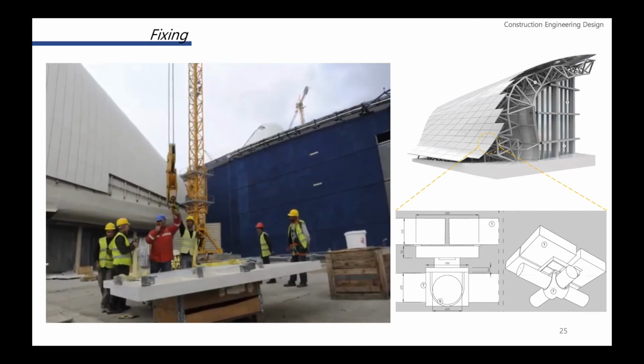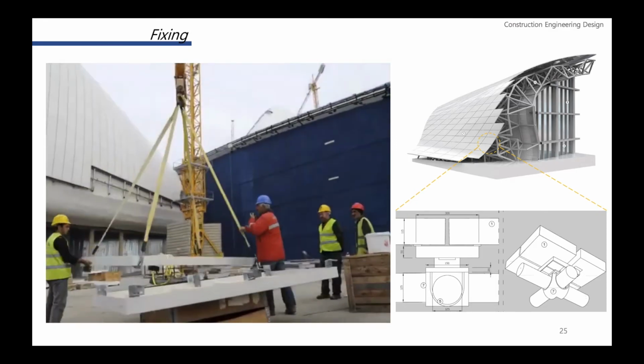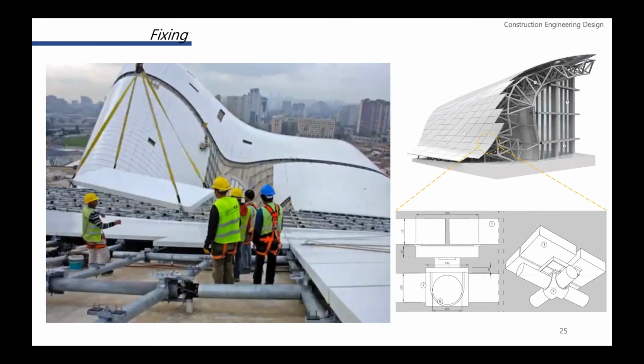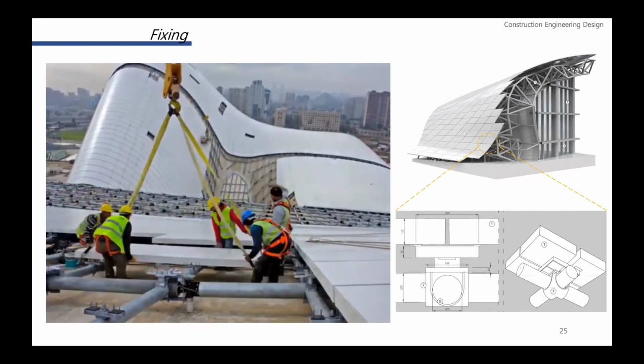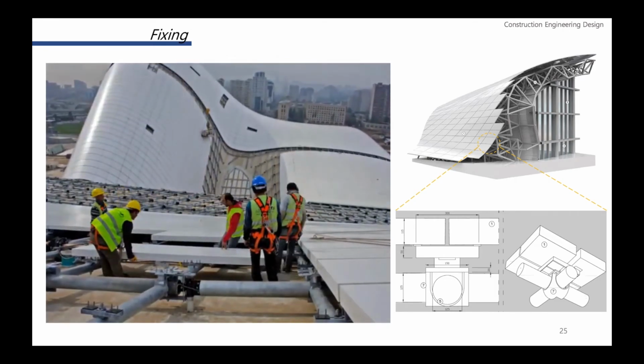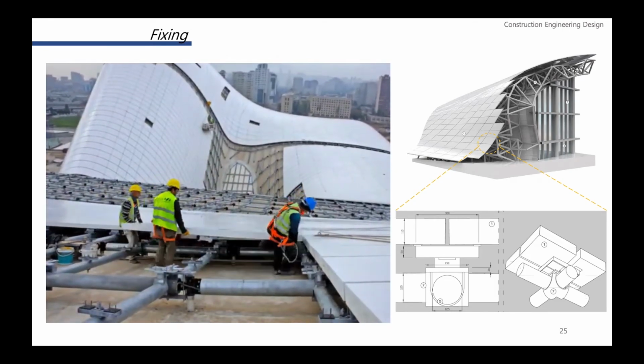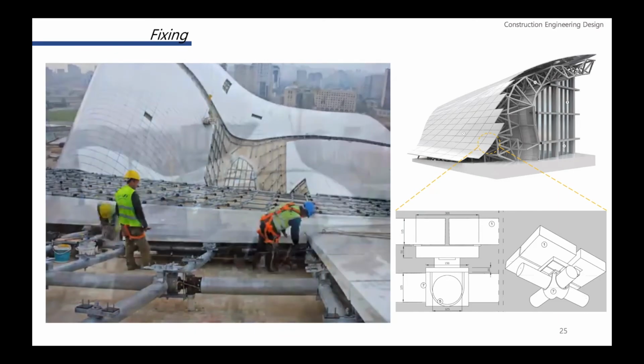The white solid skin is an open joint rain screen cladding system, which required a secondary steel substructure to fix into the space frame. The secondary steel structure is attached to the nodes of the space frame by means of rods. It spans between the nodes and between the first layer of tubes to carry the actual panel fixings.